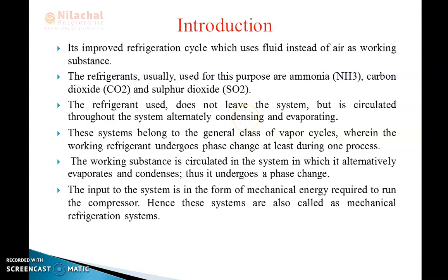The working substance circulates in the system, alternately evaporating and condensing, so it undergoes a phase change. Here the input to the system is mechanical energy required to run the compressor. Hence, the system is also called a mechanical refrigeration system. As you are giving mechanical energy as an input, that's why it is called a mechanical refrigeration system.